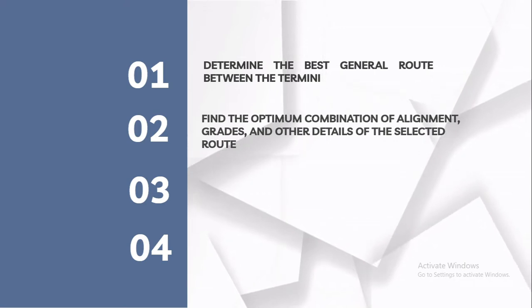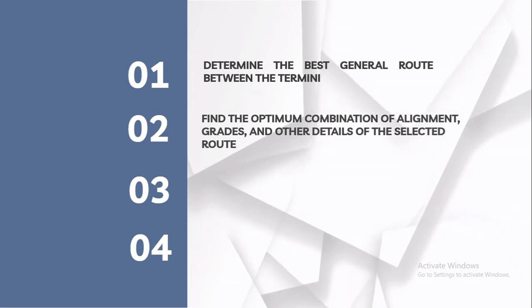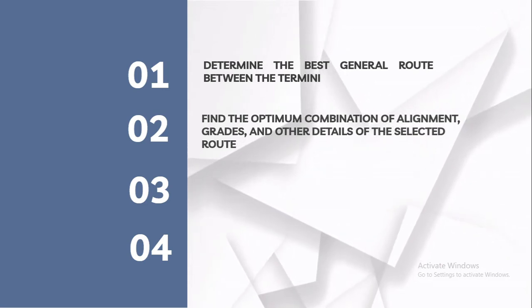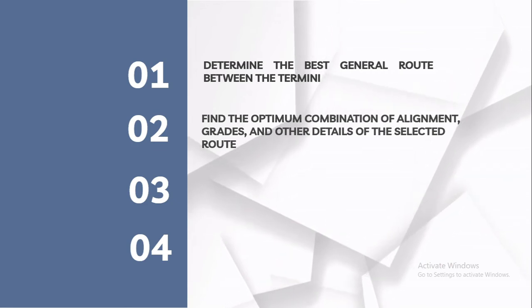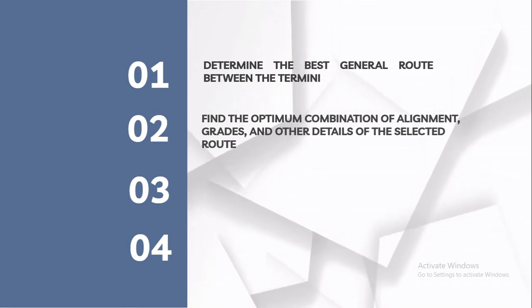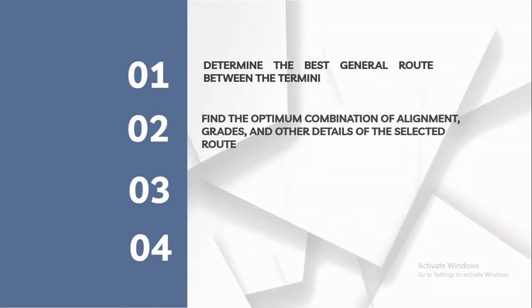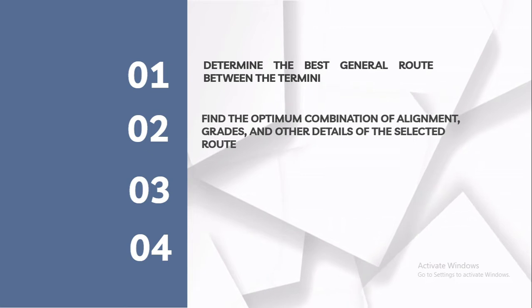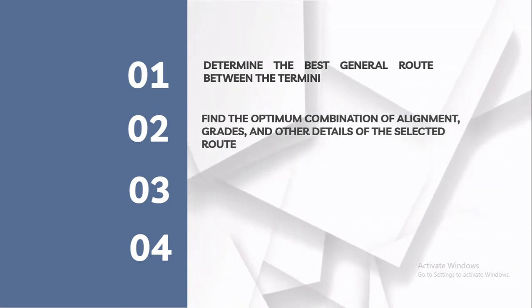It must blend with each other to produce a system that provides for the easy flow of traffic at the design capacity while meeting the design criteria and safety standards. The highway should also cause a minimal disruption to historic and archaeological sites and to other land use activities. Environmental impact studies are therefore required in most cases before a highway location is finally agreed upon.